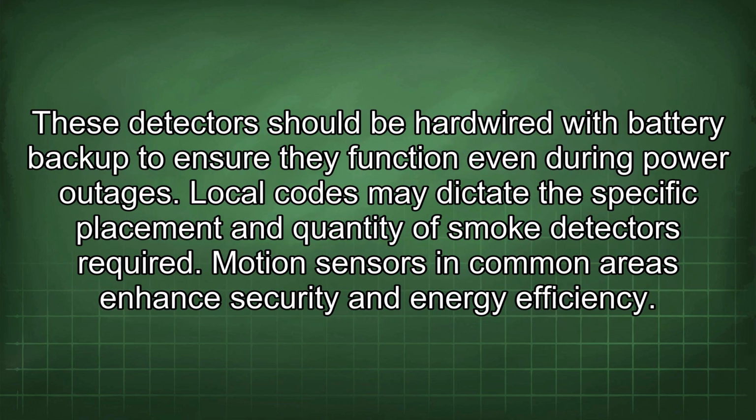For smoke detectors, interconnected smoke detectors are essential throughout the house. These detectors should be hardwired with battery backup to ensure they function even during power outages. Local codes may dictate the specific placement and quantity of smoke detectors required.